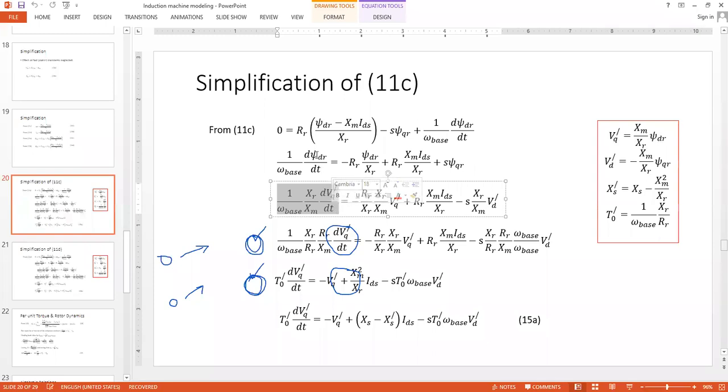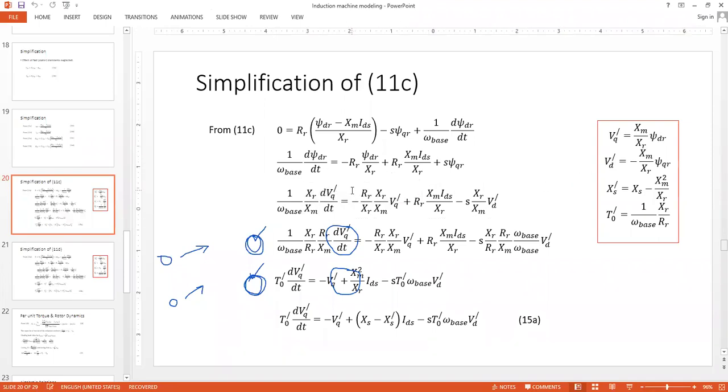So now we are not going to take the psi variables as our state variables. Instead, a more natural variable, a variable that is more known to us, that is in terms of voltages. Rather than flux linkage taken to be the state variable, we would like to take the voltage terms or voltage variables as our state variables, voltages, currents, and all those things instead of flux linkages, just to make life easy.